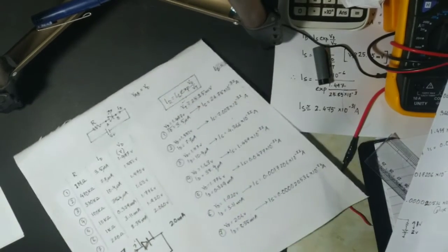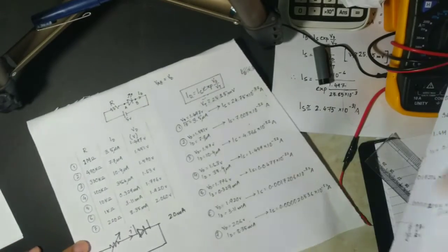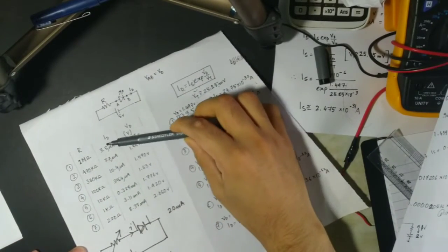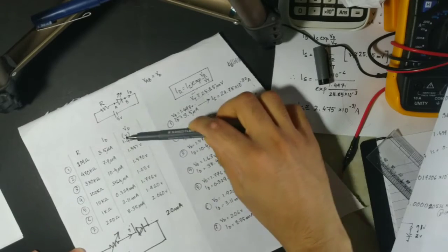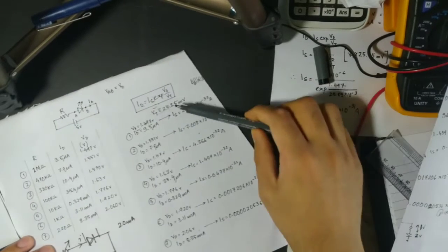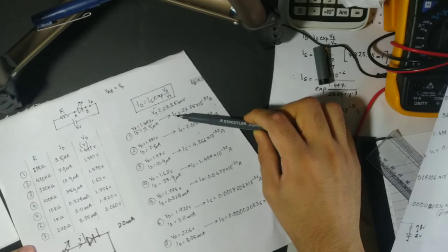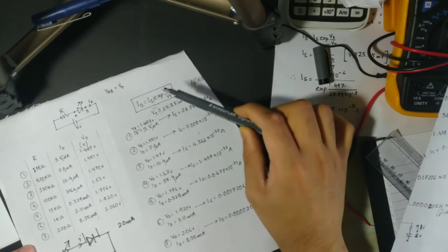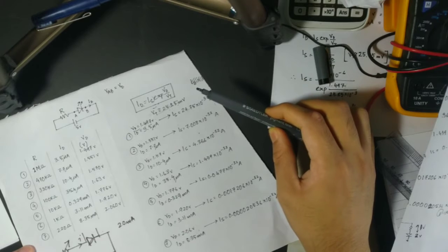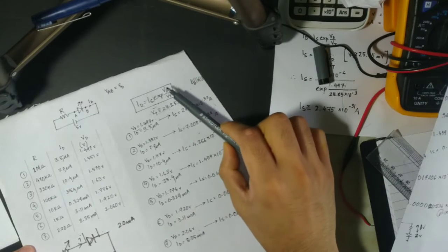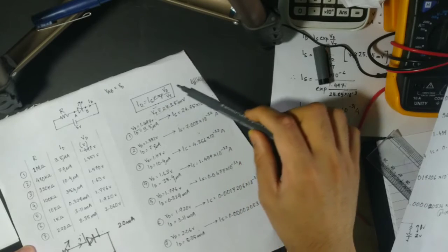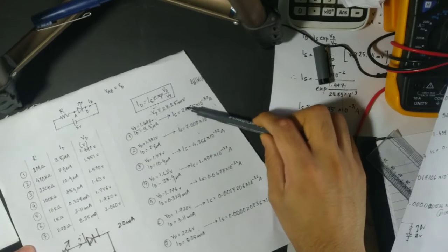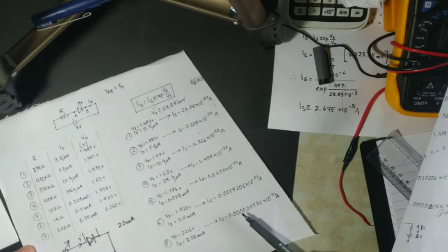Then I found that if I keep changing the resistance, as the current increases, so does the voltage drop across the diode. Then if I take out the IS values for every value, then I should get a constant value of IS, right? For every Vd and ID, if the IS is constant, then I should get a constant value, but it is not constant. It varies a lot, from 24 to close to 0.